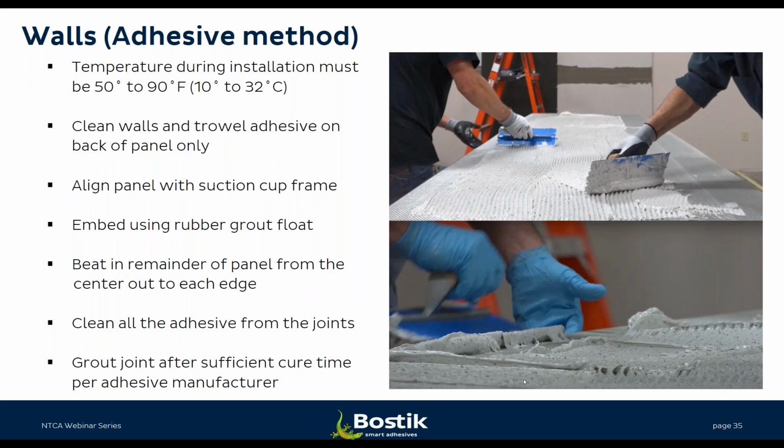There's an adhesive method now that's available for the gauge porcelain tile systems. This adhesive method needs to be combed in the same exact manner, going from east to west on a material as opposed to north and south, which is kind of what it looks like in this image. However, in this image, this is just gauging the material off the face of the panel itself, and then they'll go back and comb the material or gauge the material with the short edge of the panel.